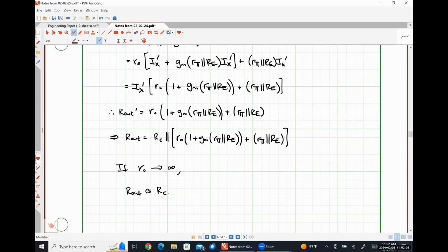Okay. So do we need to formally do that like we did the big problem the other day? We literally just represented this with an input resistance and then a dependent voltage source in series with the output resistance, and then use that as the model to do our analysis for the larger system. So I don't want to do that today because we already know how to do it. So instead, what I want to do for the next few minutes is look at MOSFETs, which will be really, really easy because it's effectively the exact same thing that we've already done.